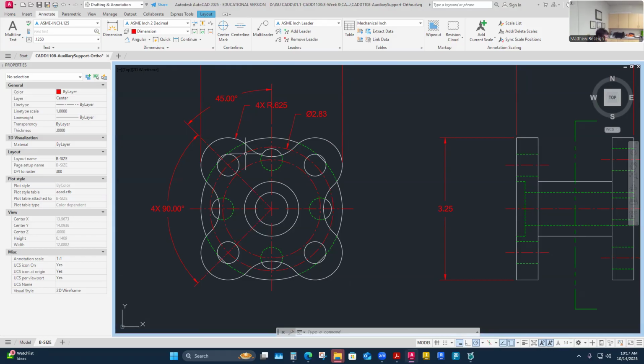It's actually chapter 10, yeah, page 305, and it is locating holes. So you have what is called polar coordinate location. Polar coordinate locating is what I just did there. I'm basing off an axis or a center, a center mark and a center through axis, and I'm establishing my dimensions. This is page 305, and it's figure 10.62.